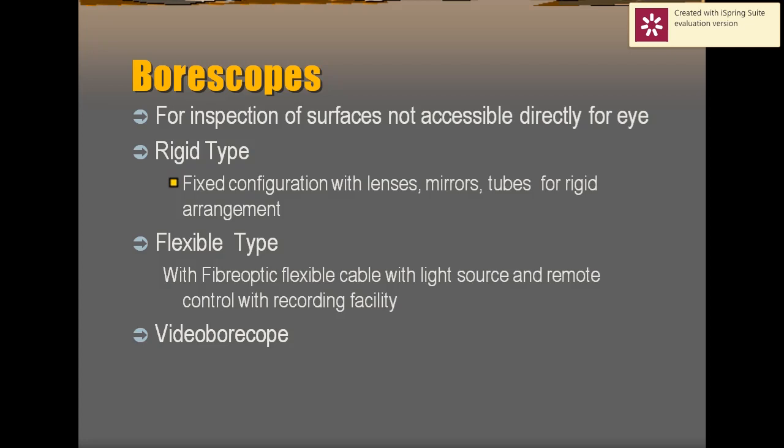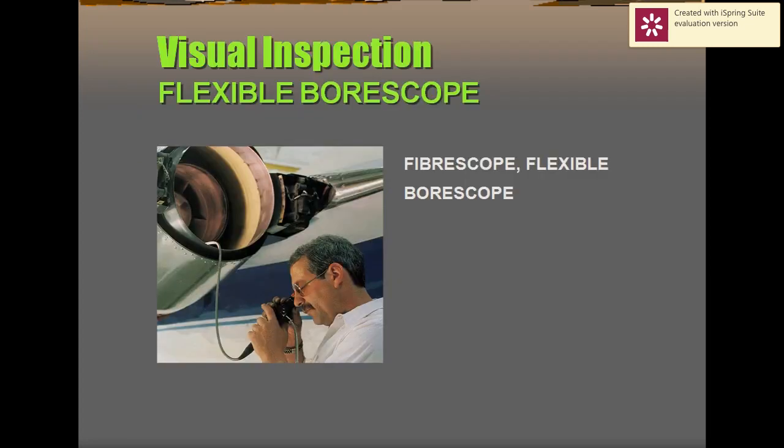As the name implies, a borescope is an instrument designed to enable an observer to inspect the inside of a narrow tube, bore or chamber. Borescopes are precision-built optical systems having a complex arrangement of prisms, achromatic arrangements and plano lenses through which light passes to the observer with maximum efficiency. This is the borescope. The person looks from the outside to see what types of defects are present inside the pipes.